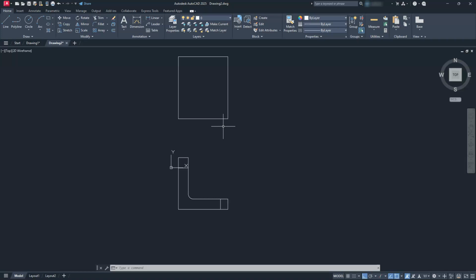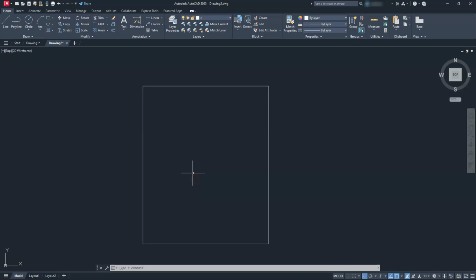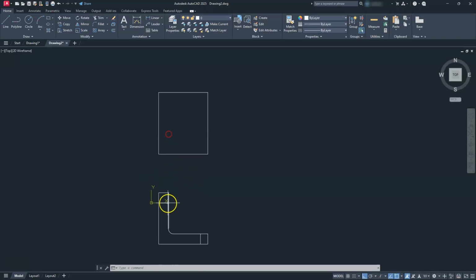And that's going to be your super important thing to remember: anytime you're creating projections of another object, these have to be in line with each other, or you're going to have to denote them with some kind of section line. All right. Now, working at this view here, we know that this edge goes over 20 because all it's doing is representing this front face here.